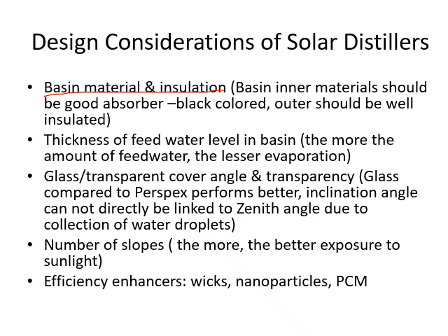Usually we make it with stainless steel because we can use different types of feed water, so we can use seawater, salt water, and stainless steel is easy to shape, so we can shape the basin easily compared to ceramic or other breakable materials. But the outer side should be well insulated. So once the solar energy is reaching the water, the water is getting heated, the hot water cannot dissipate the heat outside back again.